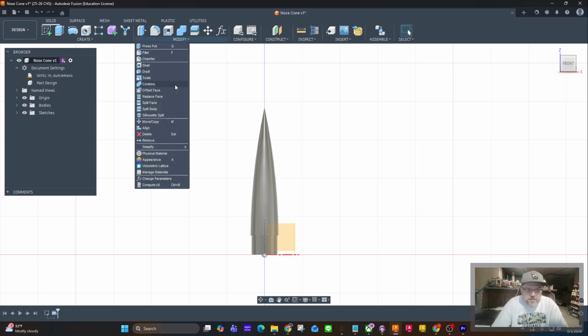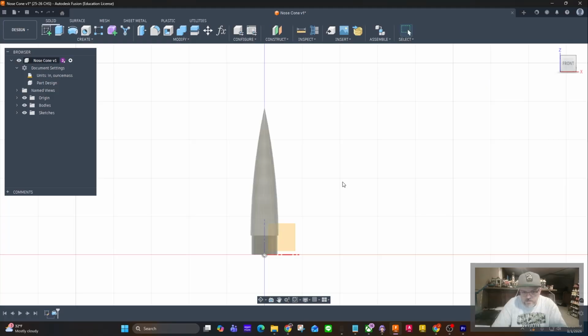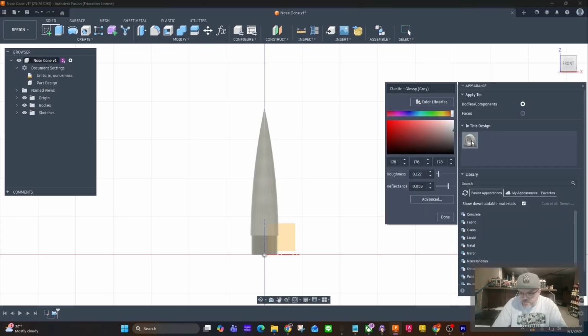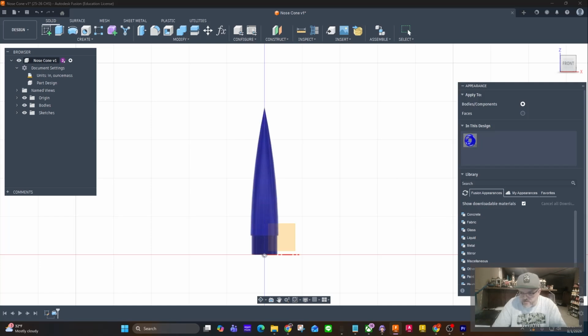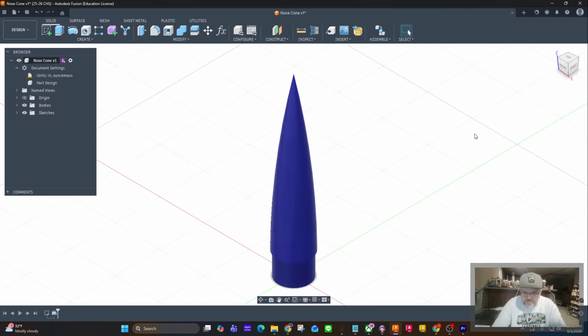Now I'm just going to do like the last couple of videos. I'm going to change the physical material, make that plastic. I went with a red body tube in my last video, so I'm going to hit A for appearance. And this one, I'm going to make it blue. We're going to go a little patriotic here. So we're going to go with the blue plastic here. Hit close. Hide that origin. And hit the home just so we can get a 3D view. So there is our nose cone.